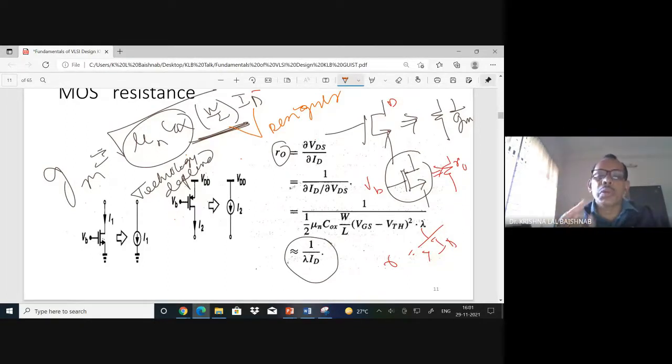Again, a point to be noted. In circuit design, analog circuit design is very complicated, because the bias point and every node has some voltage and current, and those will change if you keep changing the MOS L. Taking a stabilized point, even working in the subthreshold region, is also very challenging if we keep changing L. So for a preferable design, we keep L constant and keep changing W only.